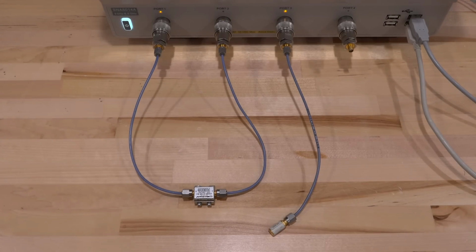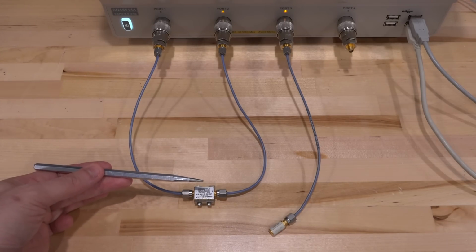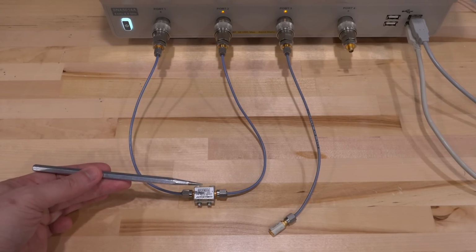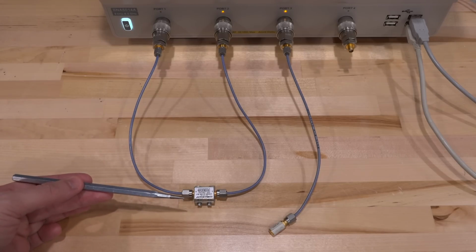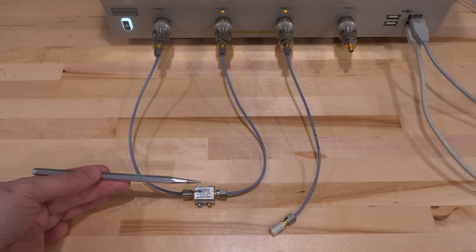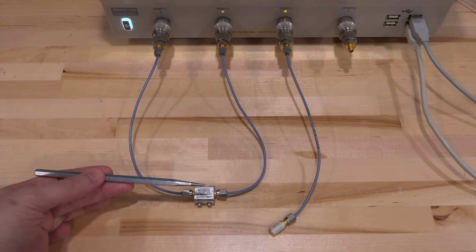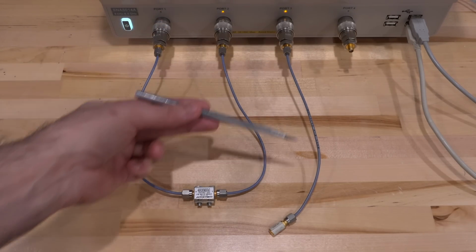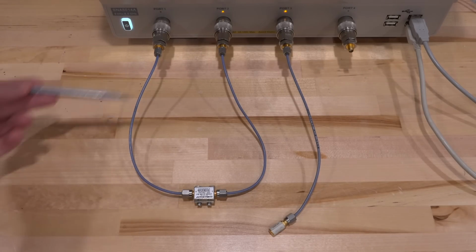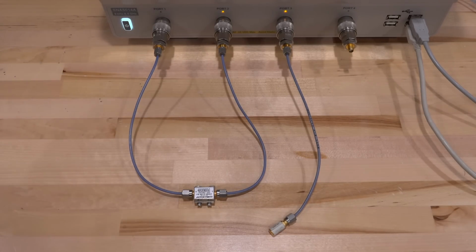Now, because the instrument gives us these interesting frequency multiplication ratios, we can begin to do some unusual things. Let's go ahead and see if we can measure a frequency doubler. This frequency doubler is supposed to work from around 3 gigahertz to 7 gigahertz or so, and I've connected it between port 1 and port 2. Of course, the frequency doubler is basically a self-mixer, but it doesn't have an LO port, so I've just terminated the LO port of port 3. Let's configure the instrument and see if we can get its frequency multiplication conversion loss.